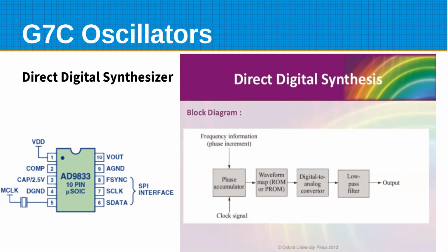Every one of those clock samples is going to be 1 degree of phase of that sine wave. So I feed that into a read-only memory, which just has a table in it, and for every degree it's got the equivalent digital value of that sine wave. So as I step through that, the output that I'm seeing are the digital samples or representations of the sine wave.